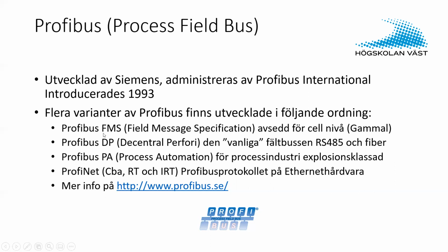But Profibus has also been extended with Profinet, which actually uses Ethernet hardware. That's a later invention, because Ethernet hardware is our normal local area network hardware. It's quite well known, very popular and cheap. So all field buses have almost adapted and tried to evolve into using Ethernet, and Profinet is one example of that.